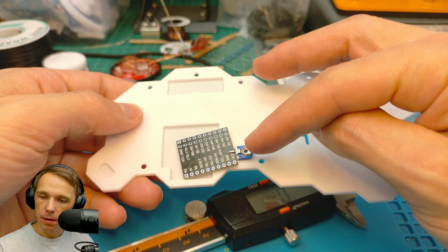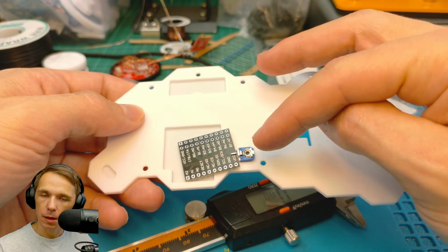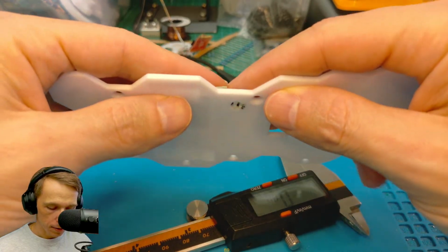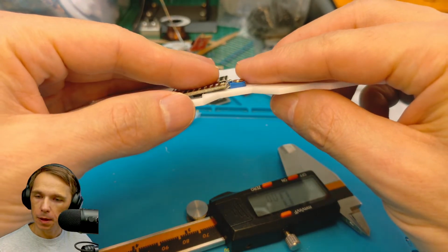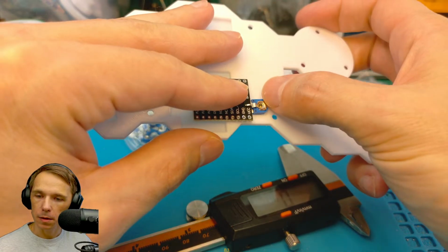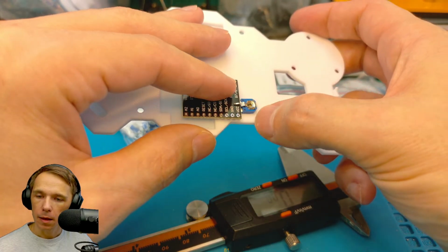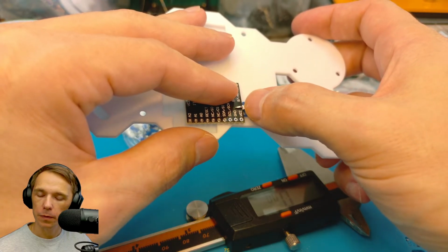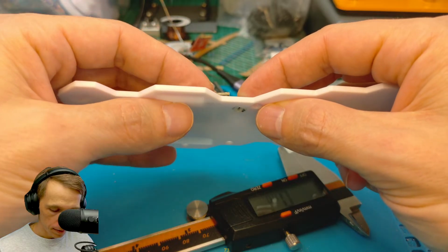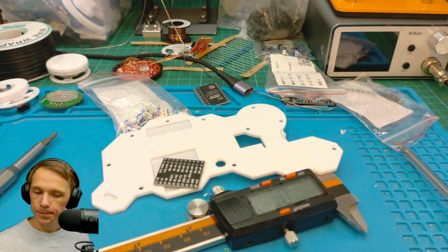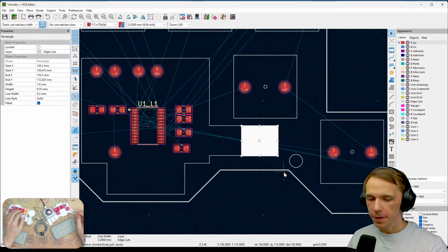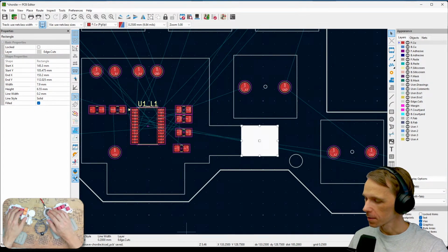The center part should be on top of the PCB, and then the other one should be at the bottom. Either the bottom one or top one doesn't really matter, because for the potentiometer the output is one of the side ones, and then we go through the middle one. Good to have something to rely on, to check what is happening.